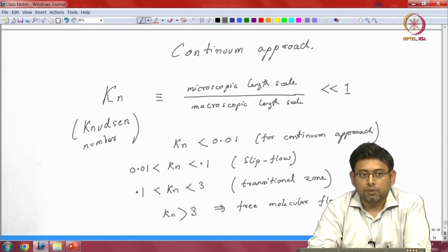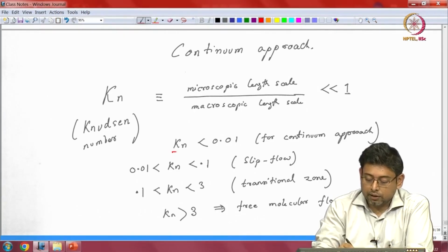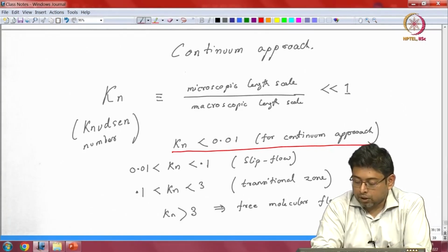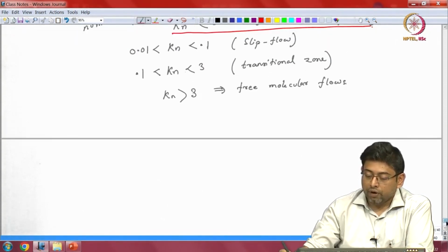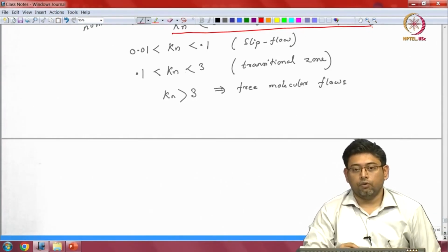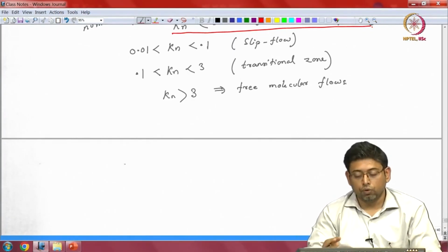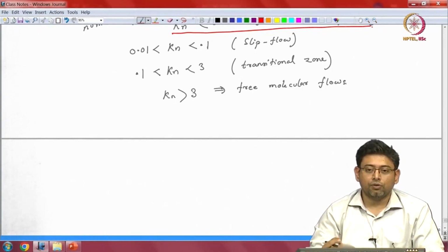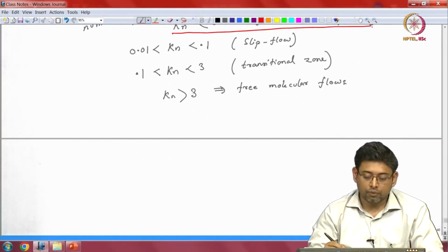So when we talk about tracer particles, we will assume that our flow is such that this condition holds and our continuum approach is valid. And this is quite important, right? Because the very fact that you are using a tracer particle means that you now actually have a proxy for the actual fluid particle. The fluid particle itself is not visible, and you want to visualize it through the use of a different particle. And obviously the idea is that the particles should follow the fluid flow properly, and we will come to that, how to figure that out, we will come to that also.